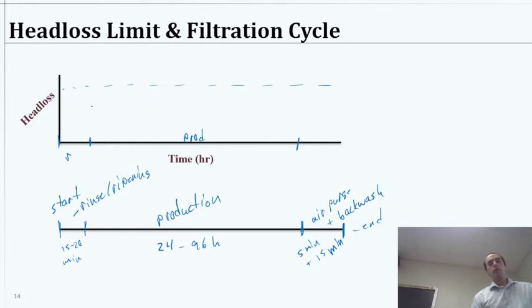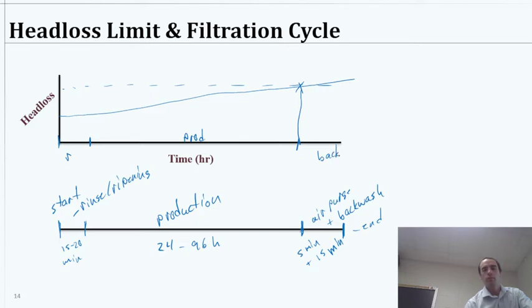Well, this one actually looks a little simpler because the head loss isn't really going to be changing very much. It's just going to be a slow, constant rise in pressure because the filters are clogging. So even in the ripening stage, it doesn't really do too much. If that's just in minutes, it's not really doing much. And then over hours and hours of operation, we hit our limit. We'll just say it's right here. There, then we stop and backwash. Okay, all makes sense? All right.